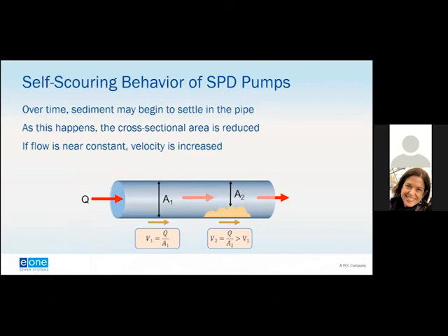So with the pressure sewer system, and it doesn't matter if it's a centrifugal grinder pump or semi-positive displacement pump, you're going to get some sedimentation that may begin to settle in the pipes. One thing we got to keep in mind, as I mentioned earlier, the pumps operate for a very short period of time. Generally, a household grinder pump will operate for no more than 20 minutes per day. So a pressure sewer system is not like a wastewater force main or a water system where you always have that pressurized flow in there. There are times when you may not have any flow in there, so you might have some sediments that settle.